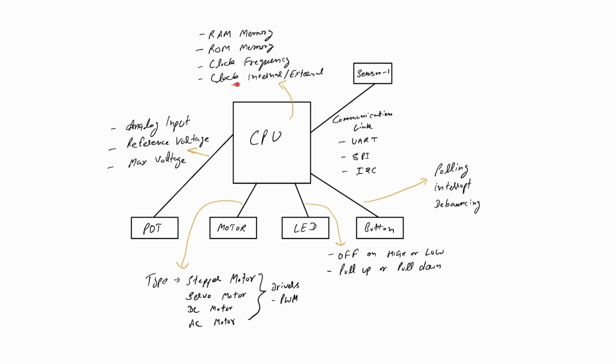You need to figure out if the clock is internal or external, which clock you are using. If you are using the internal clock, that is fine. If you are using an external clock, you need to make sure your hardware has an external crystal attached to the right pins. These are the details you will be confirming during the board bring-up phase, making sure you go through the schematic and verify all these and keep notes of them so that you can write initial drivers.